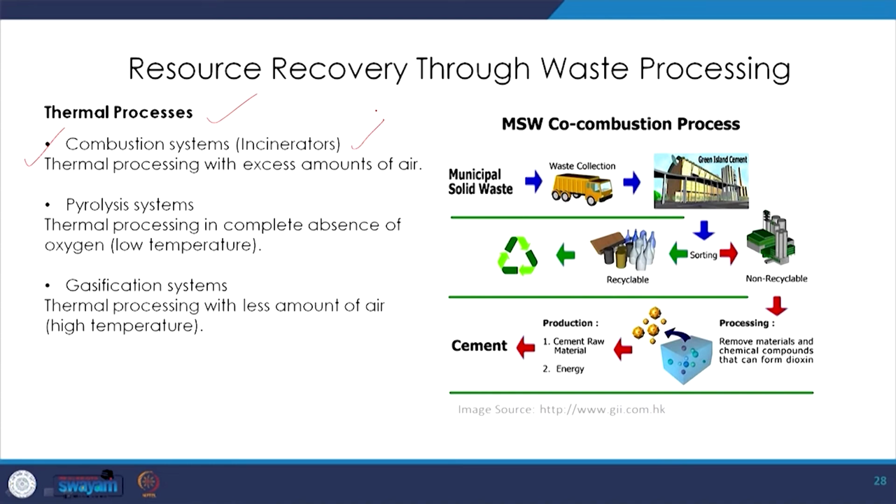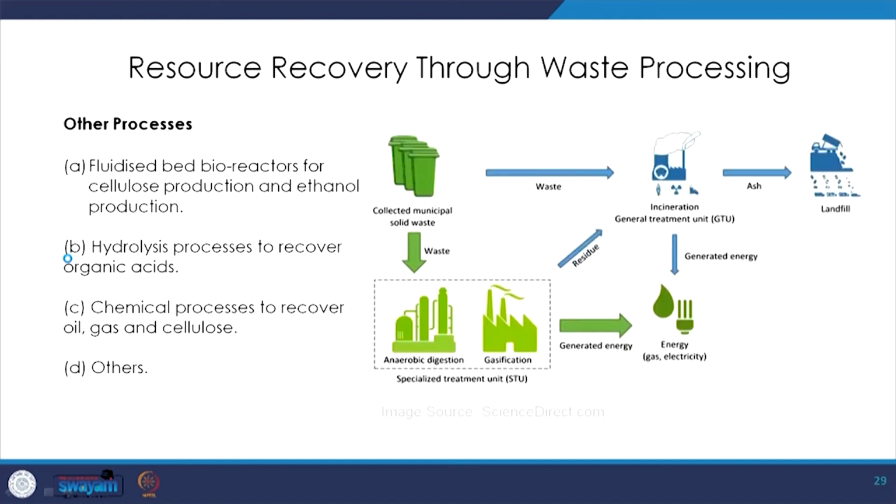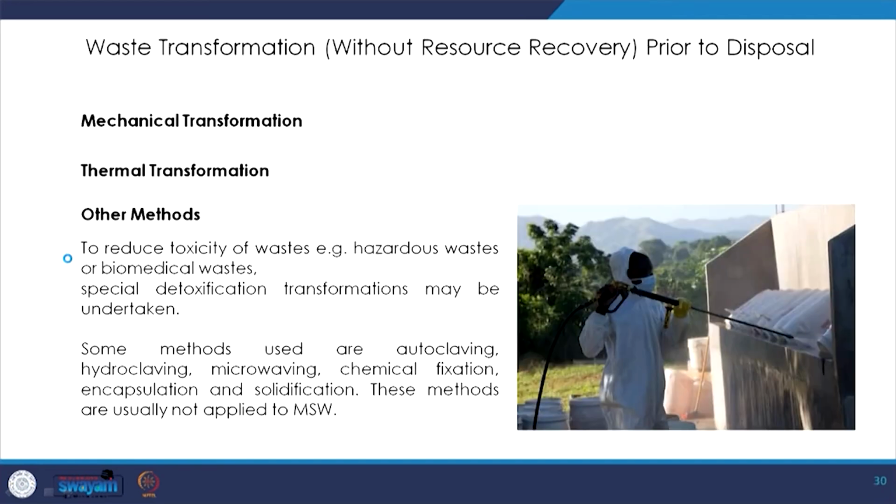So, incineration is one of the thermal processes, but all the thermal processes require a lot of energy. Then pyrolysis, where combustion takes place in the complete absence of oxygen, and then gasification, where we are combusting in the presence of very little amount of air. There are many other processes, for example, hydrolysis to recover organic acids, chemical processes to recover oil, gas and cellulose, fluidized bed bioreactors for cellulose production and ethanol production. So, a lot of technological processes are now available.